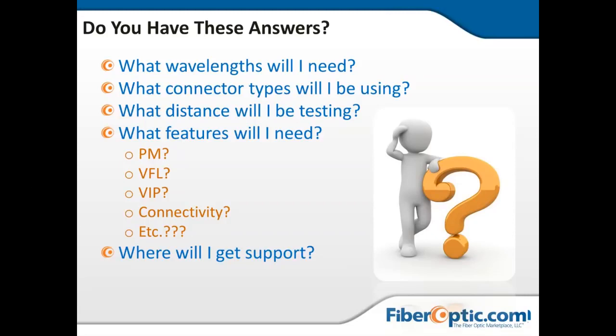And I believe what we understood the first step would be was that they would use a power meter to see if power was coming through the line. So normally this could be a separate unit, but if you want to keep it all in one, it makes some sense. So the first step would be to unconnect the fiber from the port, plug it into the power meter, get a measurement to see if any kind of light was coming through. There should be an absolute amount of power that is expected to be coming through there. And if you don't see that, then you need to kind of start to go through a series of additional tests. One of those might be seeing whether there's any damage or breaks in the fiber.